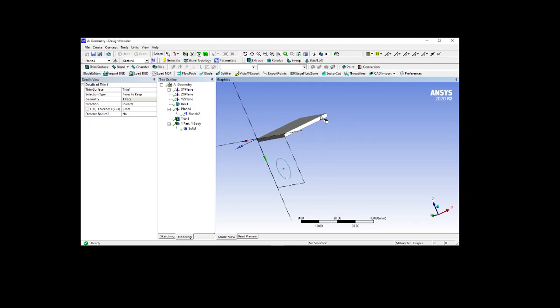This will help while you are creating a complex type of geometry where you are unable to perform the operation in a solid, but you are performing the operation in a surface manner. That time it will be helpful. Here it will contain two options, one is inward, another one is outward or mid plane. And now I'm creating the outward.